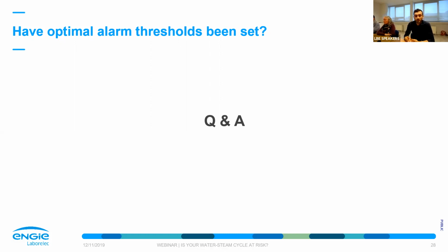Then we know that you have a lot of difficulties to achieve the steam purity guidelines. That's not a big issue. If in the past you have operated in a normal way, let's say a little bit of base load, then you can achieve those guidelines. That's already good. Then in a high flex mode, you have to focus really on the condensate and feed water train. If you have good water inside those systems, in the condensate and in the feed water, then you may also have good purity coming to the steam turbine, because in between you should have no pollution coming in. So that's the point.